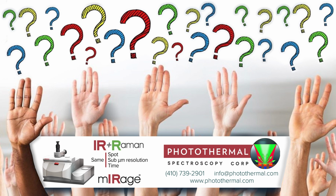Therefore, they absorb that light and heat up very quickly. So one way we overcome that for the OPTIR side is we can reduce the green probe power down to microwatt levels, like tens of microwatts, at a point where Raman won't work anymore. But we can reduce it down to that level, and then we switch to a different detector. We switch to an APD, an avalanche photodiode detector, which is an ultra-sensitive, ultra-low light level detector.